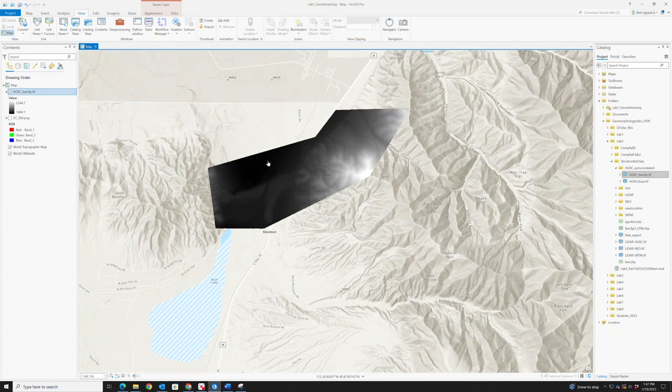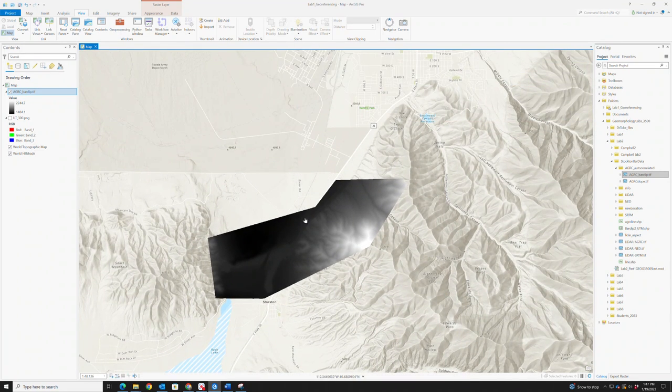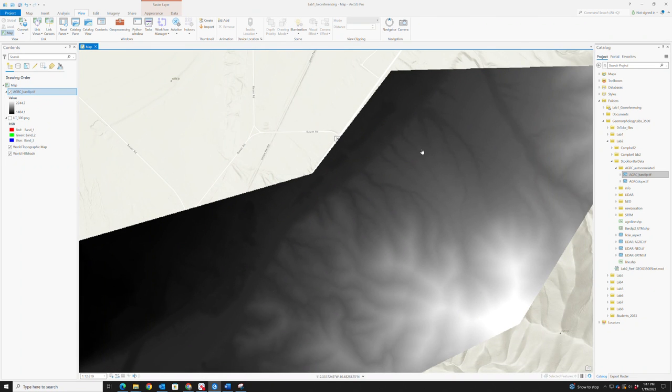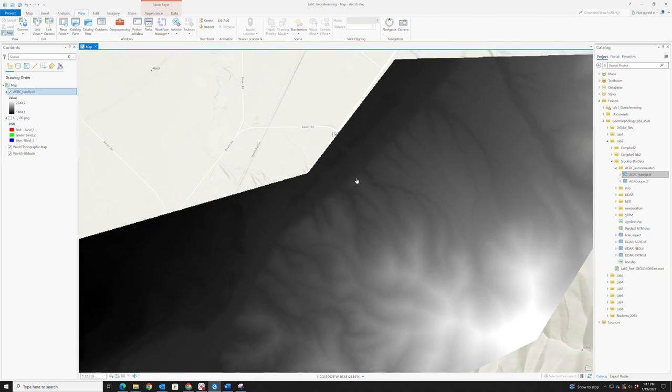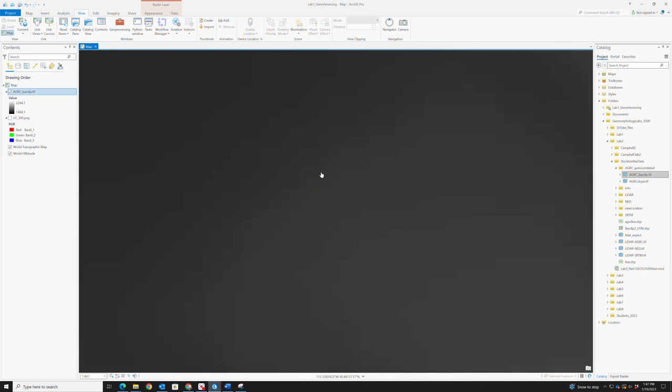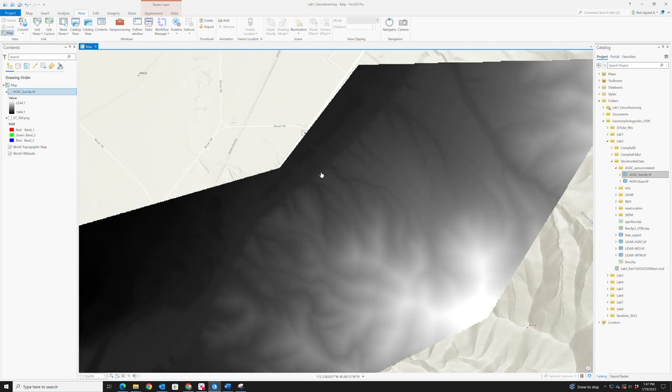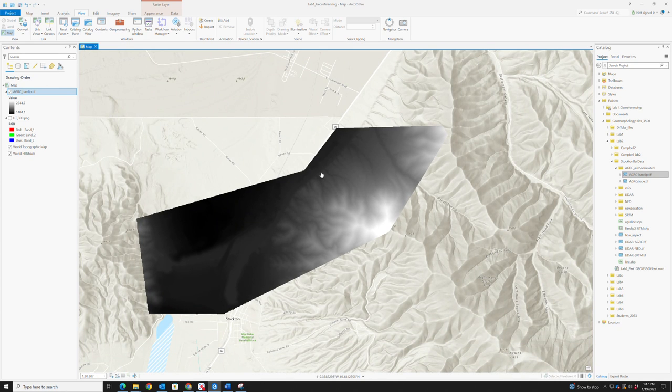And then we can see that digital elevation model appear. And if we can sort of sense the topography under there, basically it's each pixel in here. If we zoom in, we can maybe see the pixelation. Each pixel, the values of that pixel, there's only one band, and the band is tuned to elevation for a DEM. And so we can see they range from 1484.1 to 2244.7, and those values are not in feet clearly because we sit nearly 5,000 feet above sea level, so those